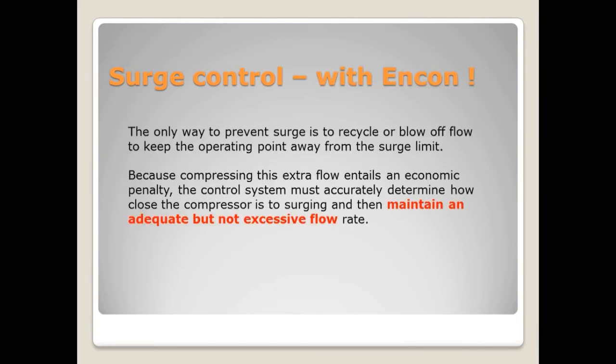Now there is a word of caution. If you discharge part of the compressed gases back into the suction section, this amounts to wastage of energy. So this will hamper the energy conservation drive. So this exercise has to be minimized. Kindly make sure that you are not unnecessarily recycling gases with the safety of the plant in mind. You should not be recycling when you are too far from the surge or the anti-surge points.